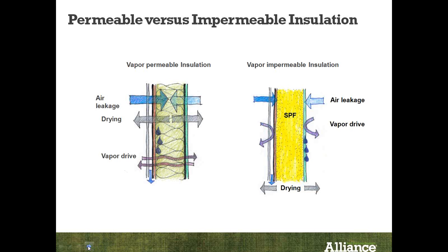And then understanding, obviously, when you have a vapor impermeable insulation, whether it's left or right or inside or outside of that board product, you're going to have drying and vapor drive occurring within its own environment. When we have a vapor impermeable insulation outboard from the cavity, we're allowing that cavity to dry inside the home, and any water absorbed in the cladding system we're allowing to dry on the outside. So vapor impermeable insulation is almost creating multiple control layers: a vapor control layer, predominantly an insulation thermal control layer, and it could be an air control layer. So it brings a lot of benefits and a lot of headaches for builders, architects and engineers to understand, because it is a complex wall assembly, and doing it right the first time makes a lot more sense.